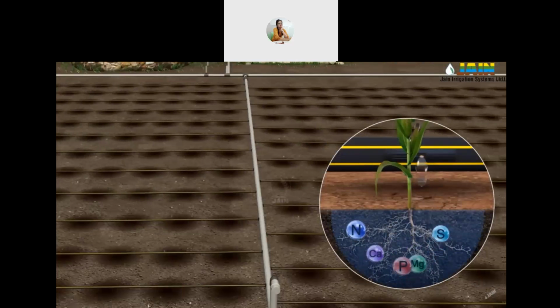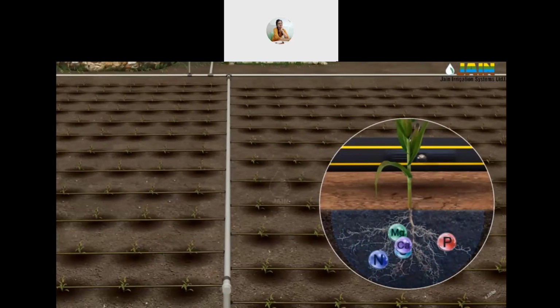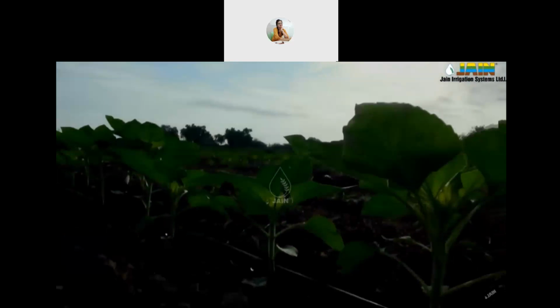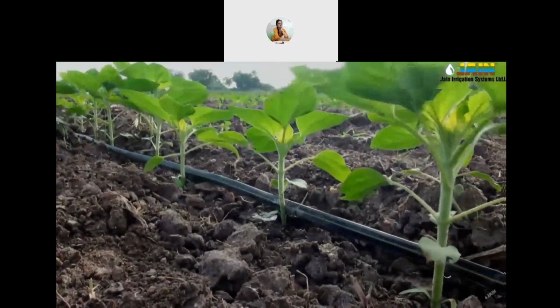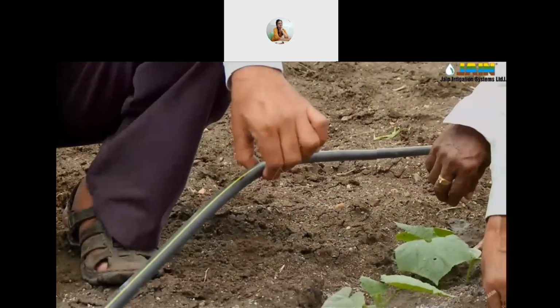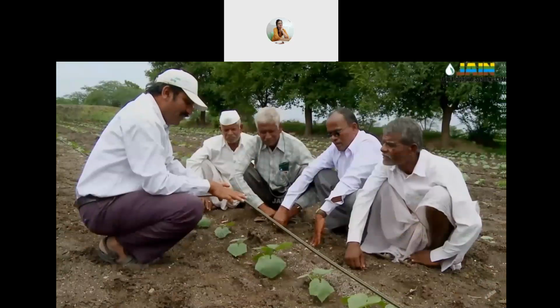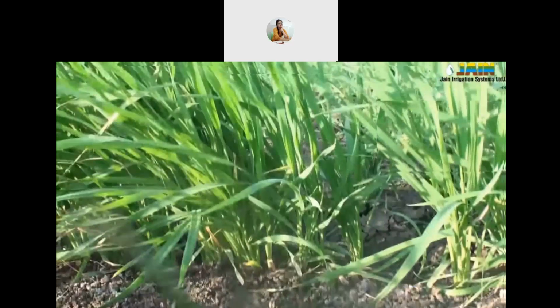Every farm is provided with Jain Irrigation's most popular 5-star rated drip line. Its state-of-the-art clog-resistant dripper design provides maximum uniformity and efficient performance for years. The system is designed to produce an application rate of 2.4 mm per day in Kharif season and 4 mm per day in Rabi season, with around 24 hours of operation per day.